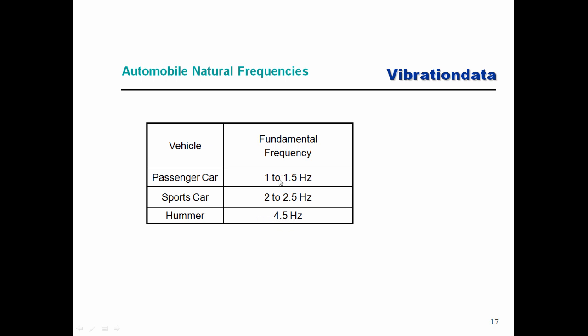Now, for the passenger car that's just going to go at moderate speeds and moderate turns, hopefully, that can be a lower frequency. And of course, the idea here is to isolate. So as the passenger car goes over a speed bump or a pothole or railroad tracks, the transmitted shock is minimized with respect to what the passengers will experience during that ride. Of course, there are some caveats, because we cannot allow the suspension system to bottom out, as that could cause something to break or cause a high frequency shock to be transmitted into the body of the vehicle itself and from there to the passenger.